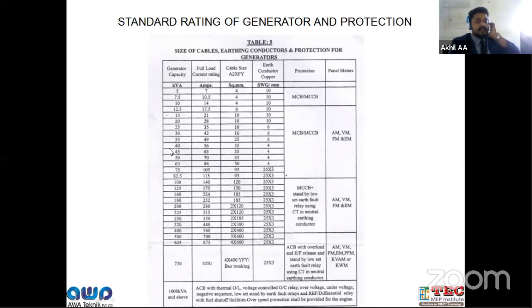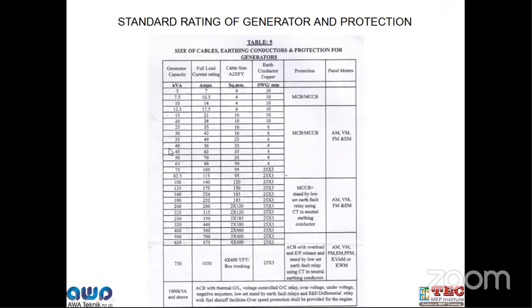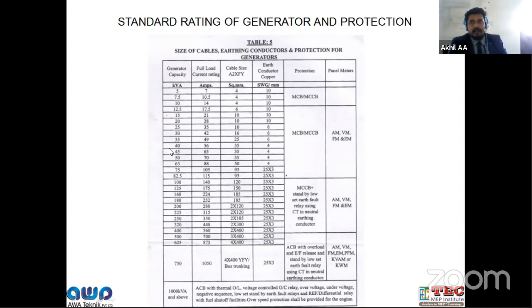For calculating the derating factors, you need to find out the conditions where you are using the cables. If you are using cables on a panel cable tray and you have a number of cables together, you have to calculate the grouping factor. The grouping factor is calculated based on the number of cables and the type of installation method.